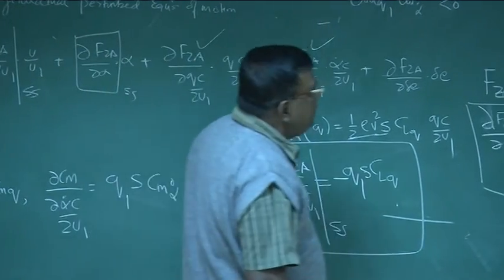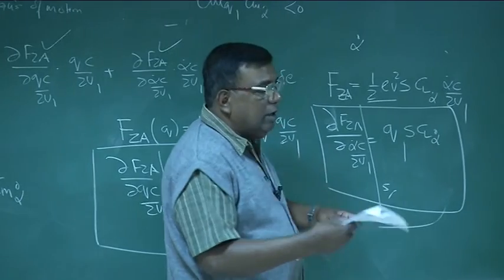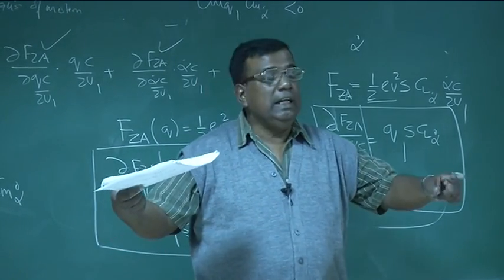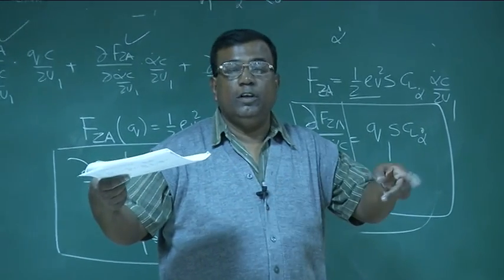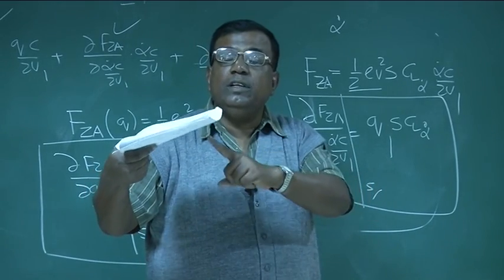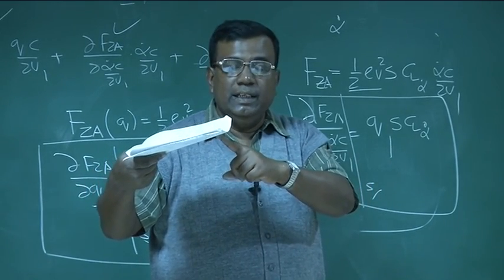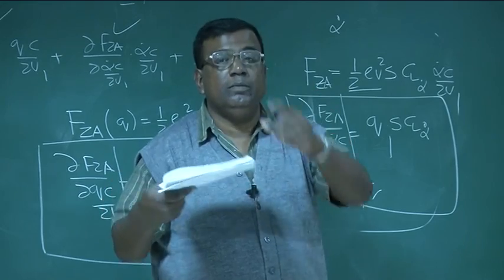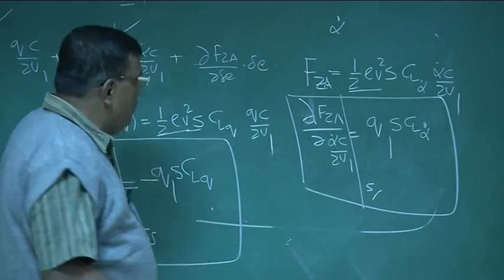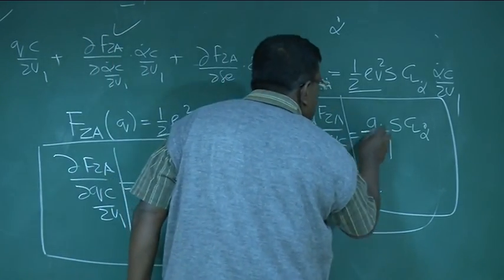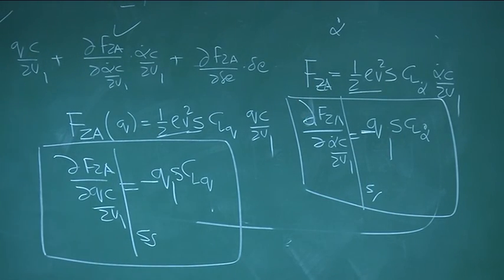Coming back to alpha dot, what is happening? Why is alpha dot coming? Because there is a delay in the downwash to come here, because vortices take time. So actually it is having, at time t, more angle, right? So that will give a force positive upward, but z is downward. So I have to put a minus sign here. Please be careful about this. Although both of these derivatives will not make much of a difference in dynamic stability for most airplanes, we should be very clear about our convention.